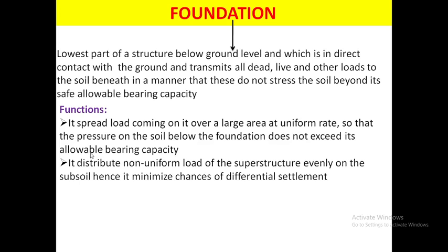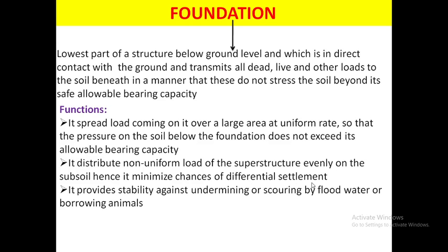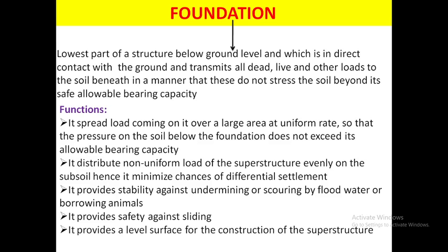Foundation distributes non-uniform load of the superstructure evenly on the subsoil, hence it minimizes the chances of differential settlement. It provides stability against undermining or scouring by floodwater or burrowing animals. It provides safety against sliding. It provides a level surface for the construction of the superstructure.